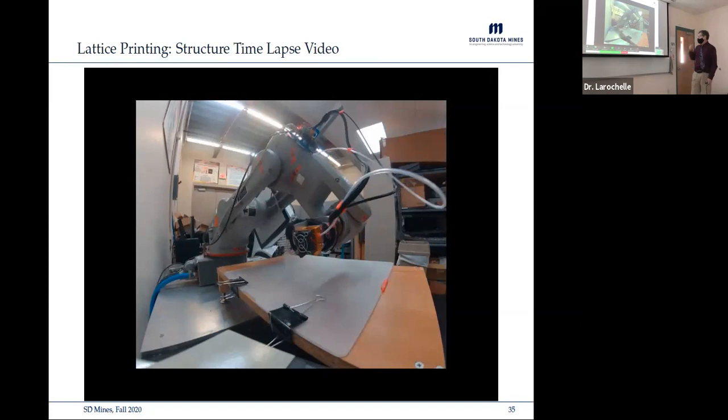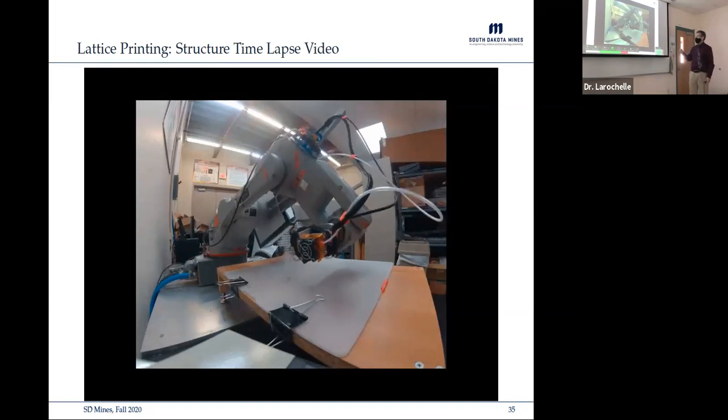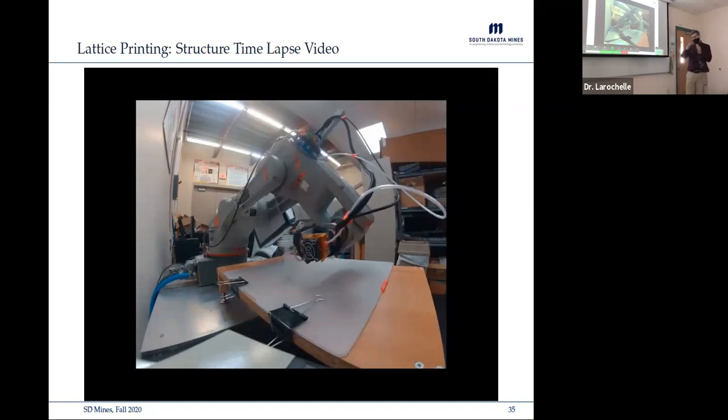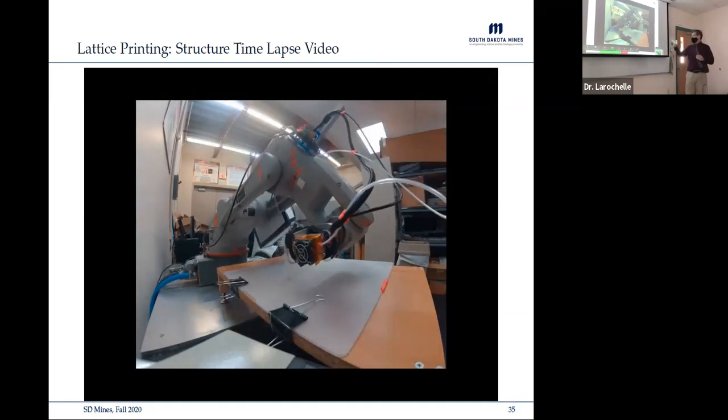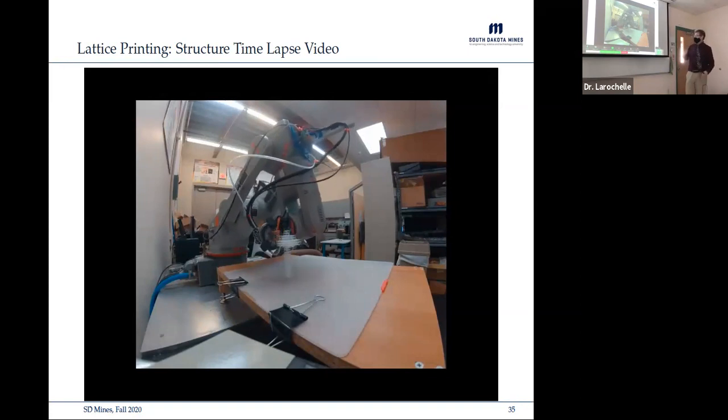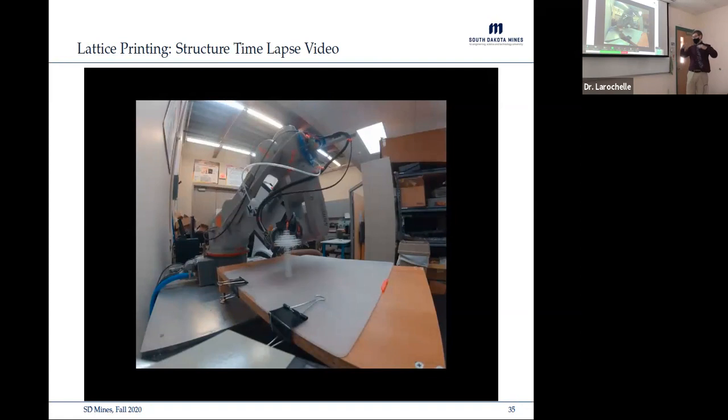Now, I haven't talked about it yet, but the segmentation sequencing also takes into account the fact that you can't put a whole lot of part mass on one side because then the structure would fall over, literally be statically unstable. So we build on one side, and then the sequencer says, okay, build on the other side to balance out the static load so it doesn't fall over.